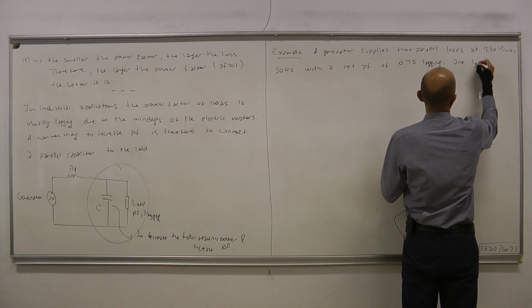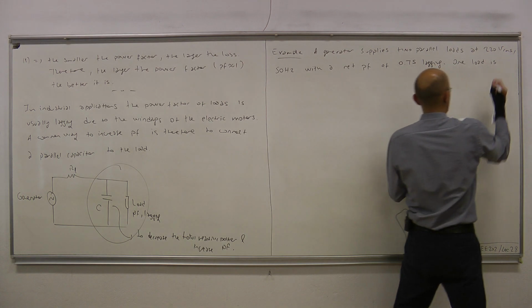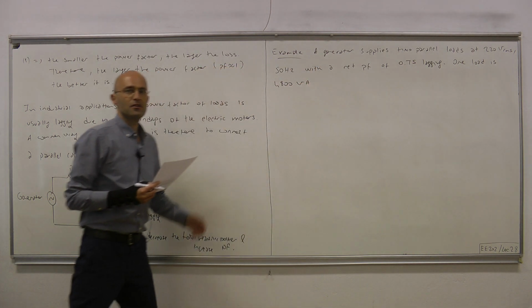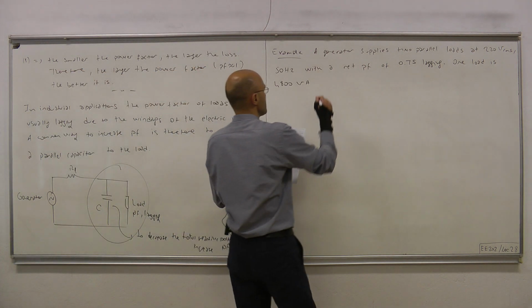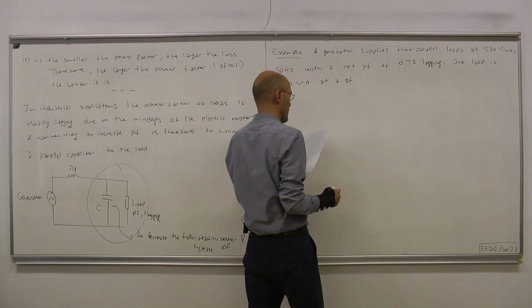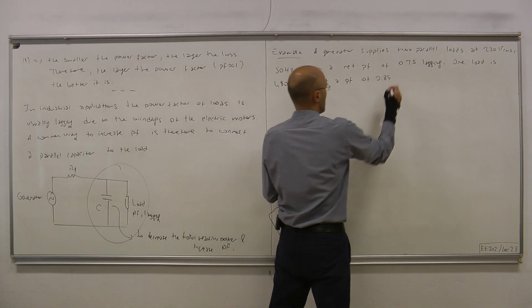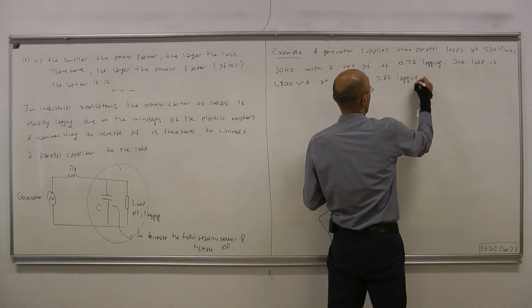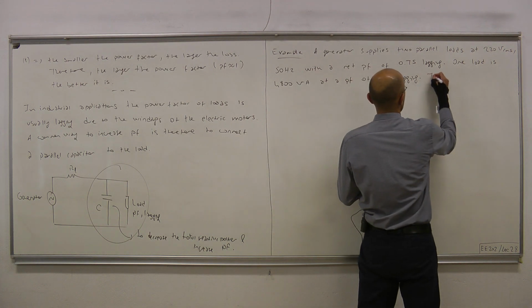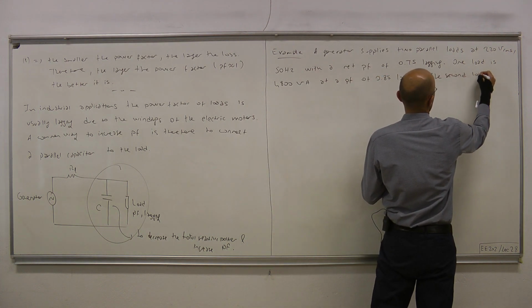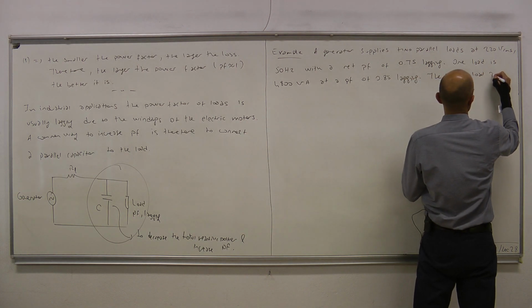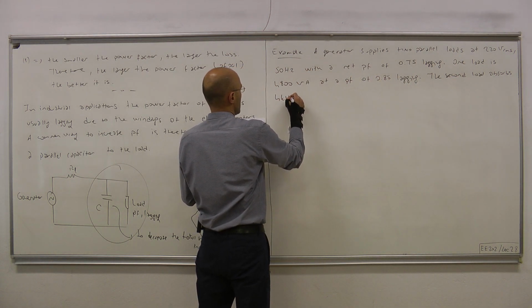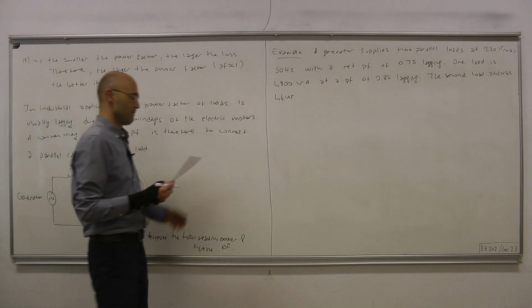Now one of the loads has 4800 volt amp rating at the power factor of 0.85, and it's lagging. Okay. And as for the second load, it absorbs 4 kilowatts of real power.